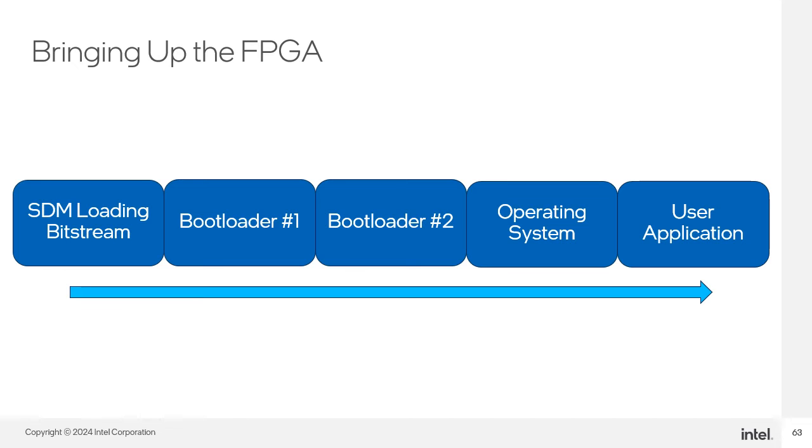The first stage bootloader is the first boot stage for the HPS. In FPGA configuration first mode, the SDM extracts and loads the FSBL into the on-chip RAM of the HPS. The SDM releases the HPS from reset after the FPGA has entered user mode.